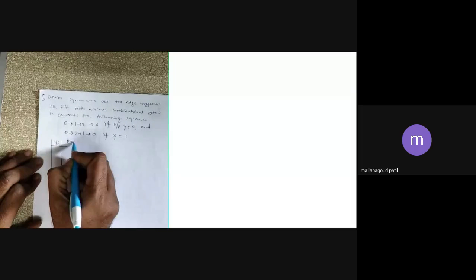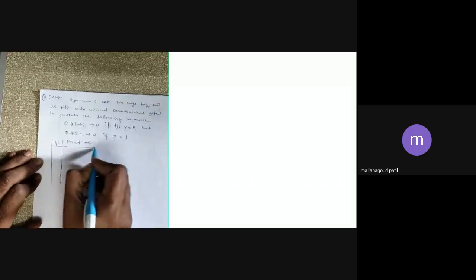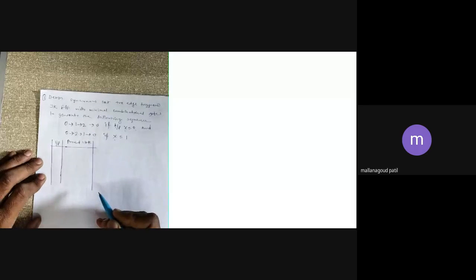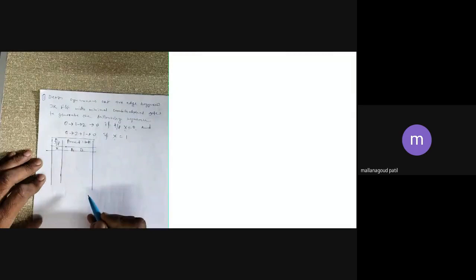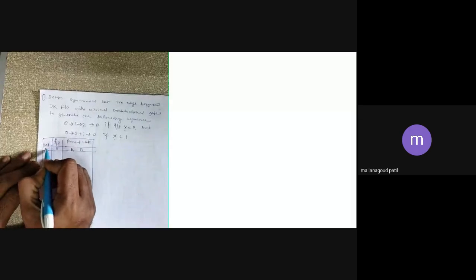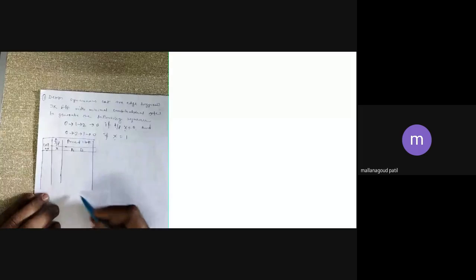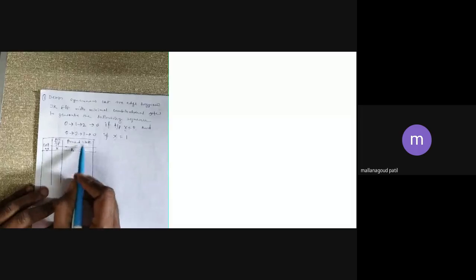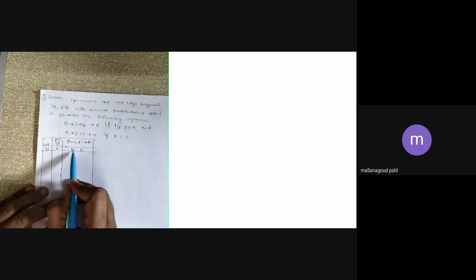Then I have the present state. You can write the present state as A and B, and the actual input X. Then this is the cell number. Cell number is not much needed for us; you can write it or not. How many total inputs are there? One is the actual input. Two are the present state, that is QA and QB. Instead of A, B you can write QA and QB, otherwise you have confusion.